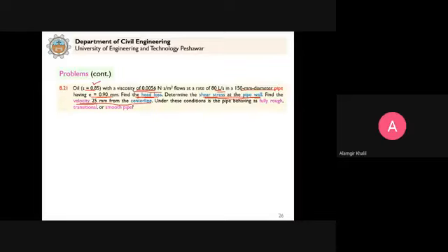Remember, if you want to calculate the velocity at 25 millimeter from the center of the pipe, which equation do you have to use? Because we have a parabolic equation for laminar flow and a logarithmic equation for turbulent flow. So first we have to determine what type of flow regime occurs for these given conditions. Clear? And then we have to see whether the pipe is behaving as a fully rough pipe, in transitional mode, or as a hydraulically smooth pipe.